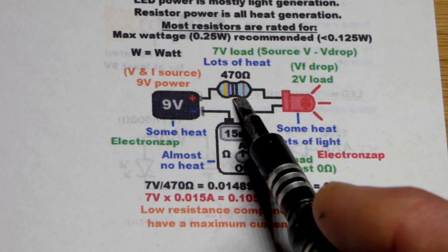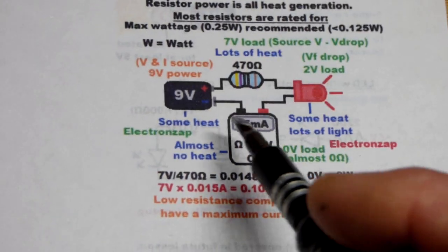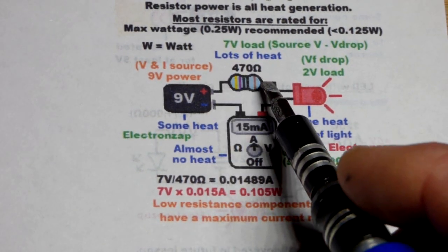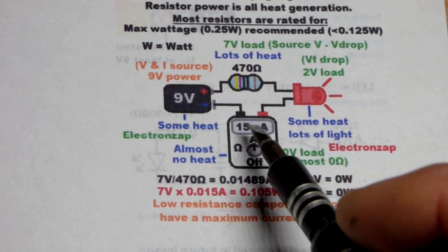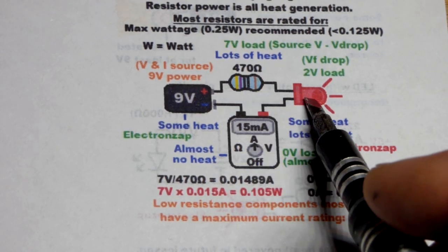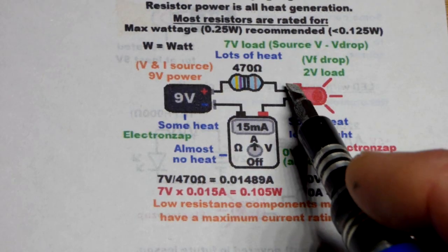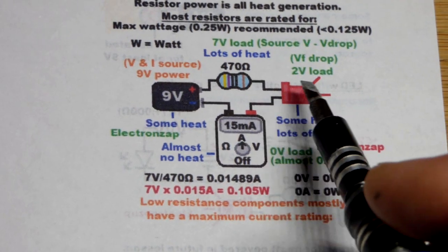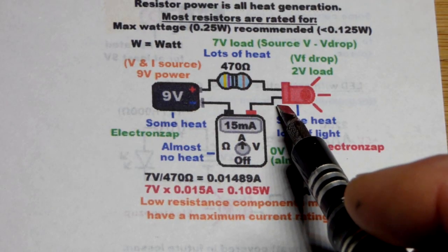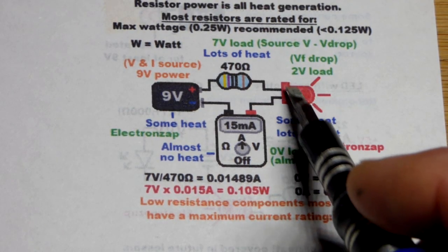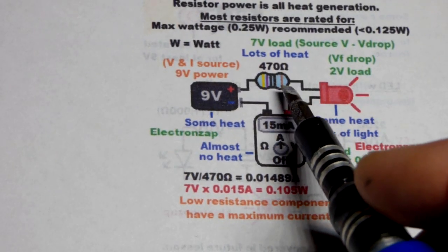When it comes to resistors, it's a bit more complicated. As voltage goes up, current goes up. And so it doesn't maintain a steady voltage like LEDs do. And that's one way you can get a reference voltage. If you want circuitry that can tell if it goes above or below about 2 volts right there, you could use a red LED to set a reference voltage. Resistors, you can't do that.